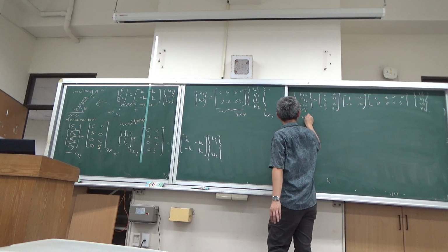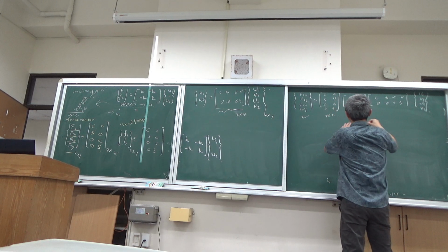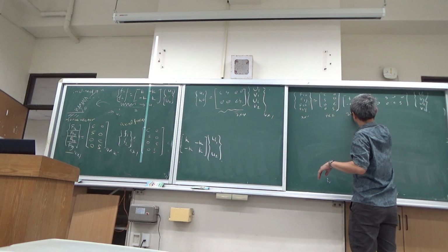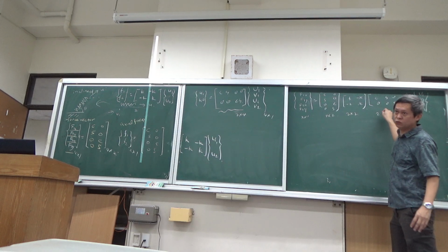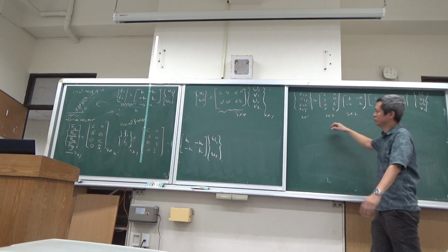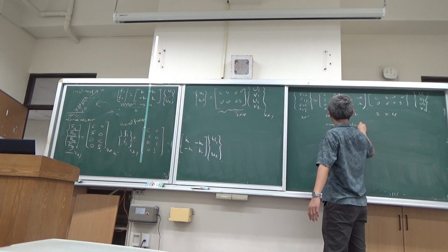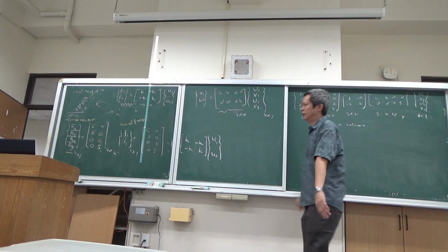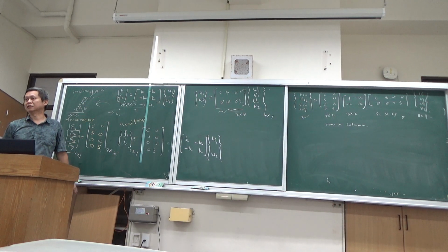So I repeat, this is the 4 by 1 vector of force. This is a rotational matrix, being 4 by 2. And this is my 1D stiffness matrix, 2 by 2. And this is another rotational matrix, 2 by 4. If you are not sure, we are talking about row times column. How many rows and how many columns? In this case, this is a 4 by 1, 4 rows, 1 column. So this is a column vector. Okay?